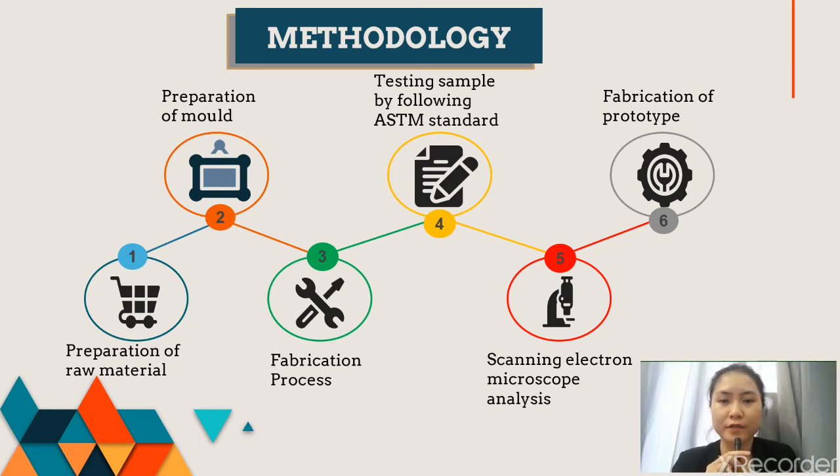Next is the fabrication process. In order to obtain a layer of layout, kenaf fiber and fire retardant are mixed together. First, pour the fire retardant liquid into a basin. Then, soak the kenaf fiber in the fire retardant liquid. This process will take around 24 hours for the kenaf to absorb the fire retardant liquid.